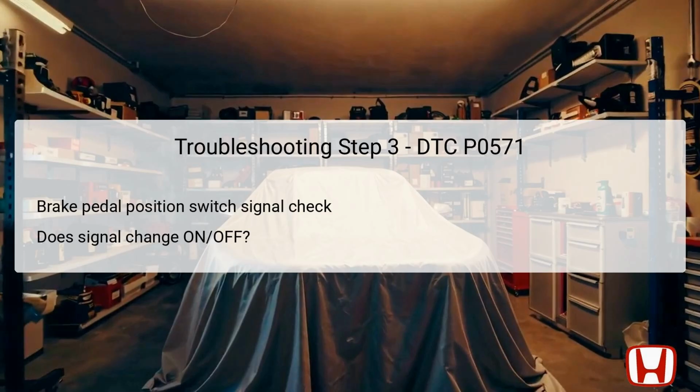A clear change in status indicates that the switch is functioning correctly at that moment, even though intermittent failures may still occur. If there is no change in signal, this likely points toward a malfunction within the switch itself or its connections. It's important to check for possible loose connections or damaged wiring at this point.